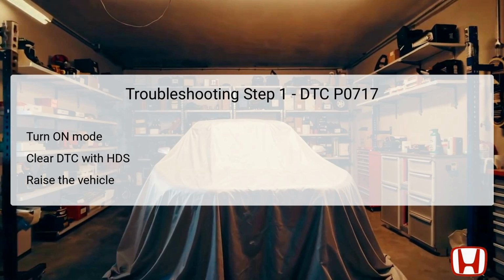After clearing the DTCs, the vehicle must be raised securely on a lift, ensuring that all four wheels have the ability to rotate freely. This setup is crucial for subsequent tests where real-time data will need to be captured while the vehicle is in motion. It sets the stage for determining whether the issue is intermittent, as retrieving accurate DTC data requires vehicle operation under specific conditions.